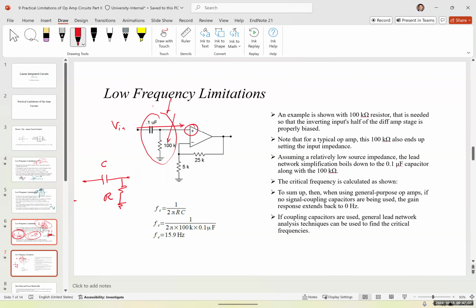And in the next chapter, where we speak about filters, I will explain the difference between a first order and second order. Second order has a better response, better slew rates, a sharper response, but you need more parts. It's going to be more expensive and it creates its own challenges.